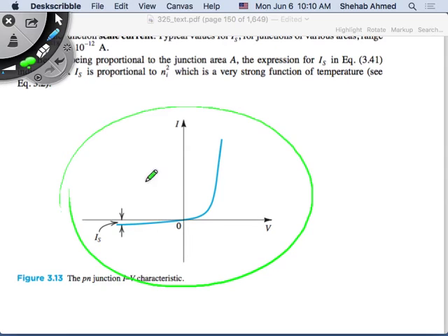Okay, so remember, now we discussed 3 models of the diodes. There's one that is ideal. Ideal meaning anytime you put it in reverse bias, it will not conduct any current. I'm here at 0. And anytime that I have the diode in forward bias, I will ignore this barrier voltage, and I will have as much current as possible. This current is limited. You have to limit it by your external circuit, otherwise you will bypass the power dissipation limit of the device. So this current theoretically can go to infinity, but that's why you have to make sure that your circuit limits that current.